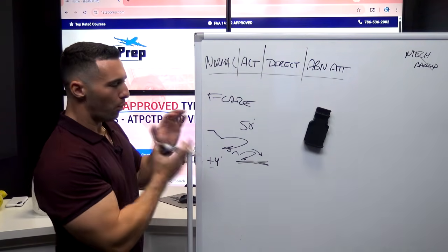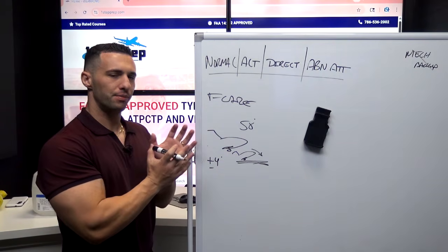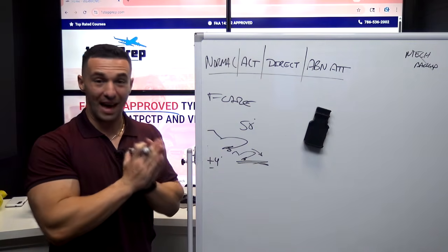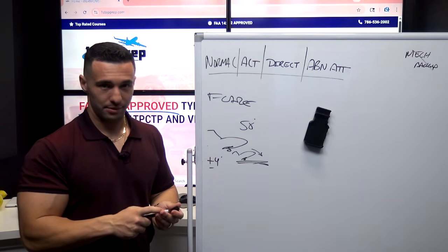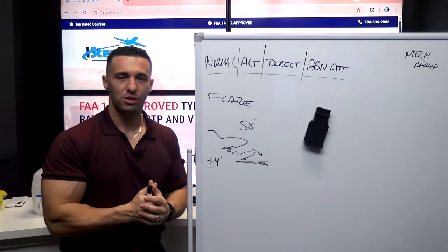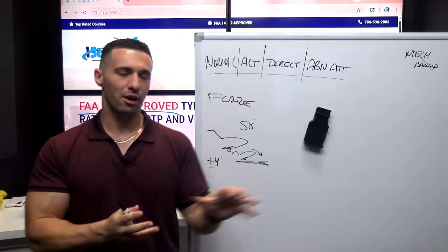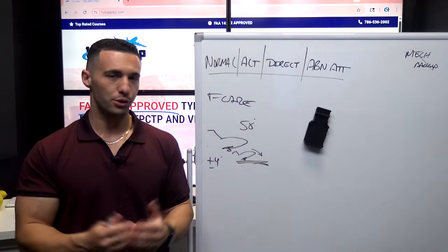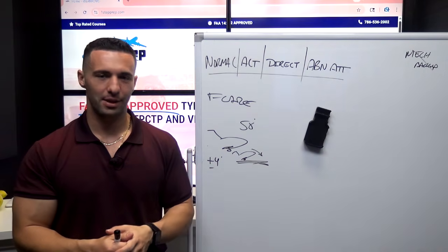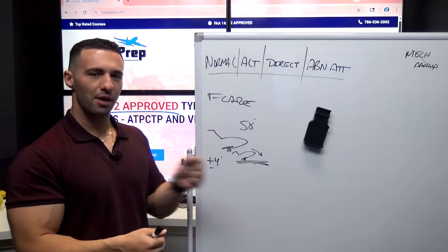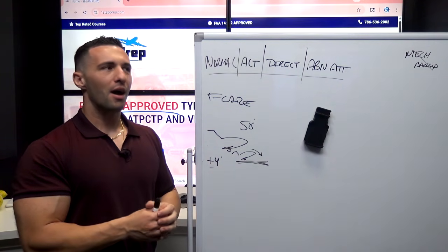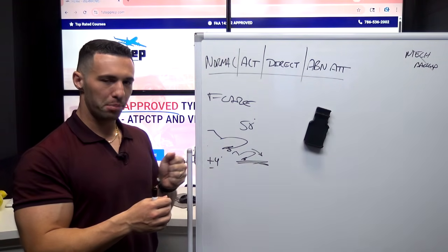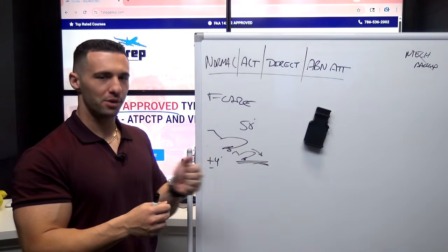Now, why do we need this? I want to turn your attention away from this for just a second, and think about any other airplane you have flown that is not an Airbus, from a 172 to a 747. If you think about your landing flare, and you can just Google a YouTube video on cockpit 737 landing video, you're going to see the inputs that are being done on this column. They're not one continuous aft input to a touchdown. They're generally an aft input followed by a neutral input to an aft input to a neutral input.